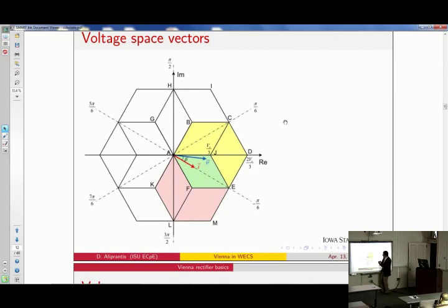So basically what this is telling you is that the voltage can only deviate from the current by plus minus 30 degrees. Okay? So that gives you a constraint. In electrical engineering, we call this a constraint on the power factor angle of this topology. Apart from the angle, you cannot be outside this little parallelogram. It also gives you a constraint on the magnitude of the voltage.